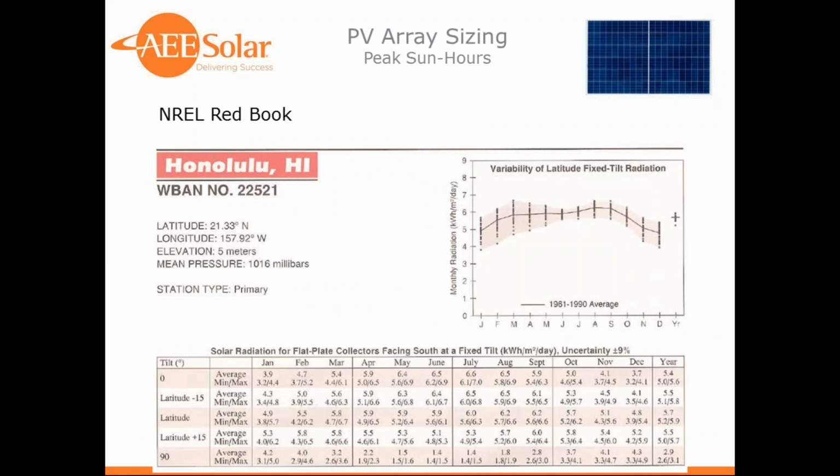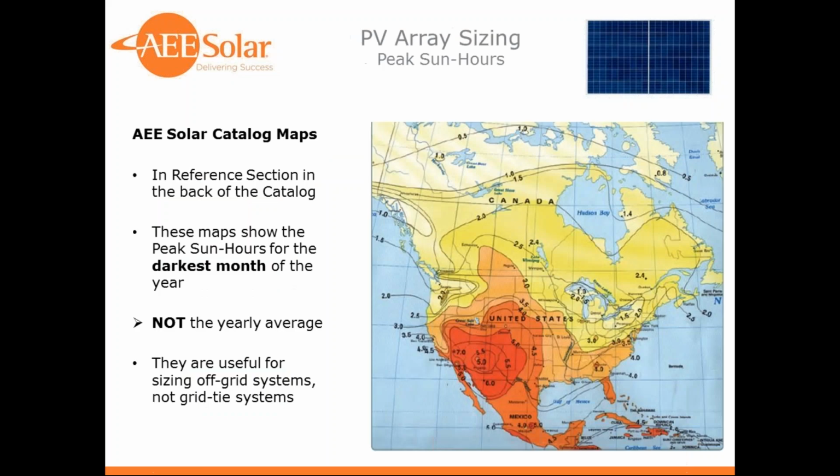So we get into PV array sizing, and obviously we have to find out what the peak sun hours are. There's a number of sources for that. National Renewable Energy Lab has their Red Book, which has excellent data collected over 30 years for every month at multiple locations around the country. So that's a great source to do it.